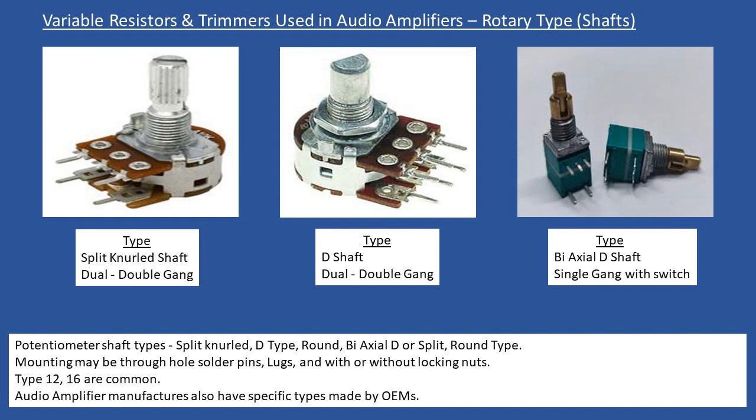And then when I talk about OEMs, I'm talking about original equipment manufacturers, and this is where audio amplifier companies go out and ask for a specific design of potentiometer to be made to their specification. And it's not uncommon sometimes that you have to take a generic potentiometer and try a workaround, maybe extend the lead lengths here to get it to fit onto an older type amplifier.